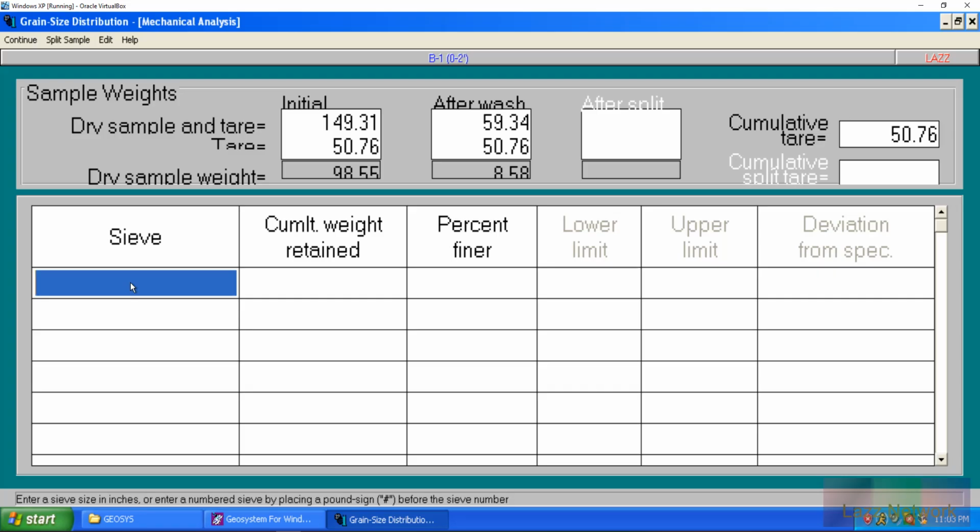And where that really comes into play, especially, is if you're doing aggregates that have those sieve envelopes that I talked about. Because remember, some of those said, depending on your aggregate size, okay, well, 100% needs to pass the 1.5 inches. So if you start off with the 1 inch, hey, you have material retained. Okay, well, that's fine. But did you have any rock retained on anything greater than 1 inch?